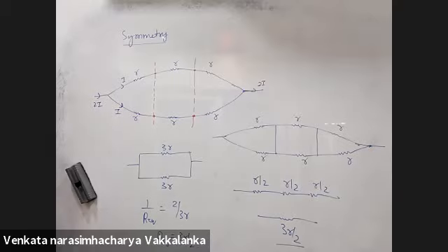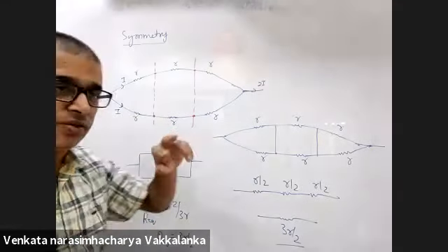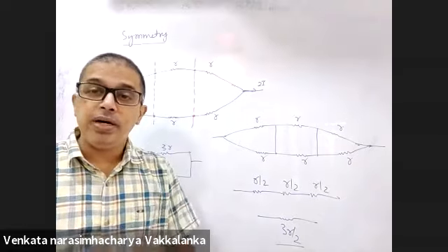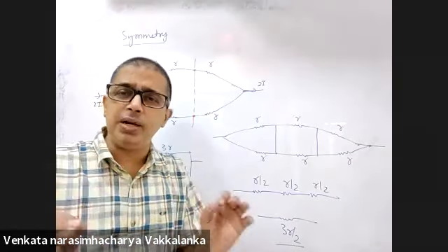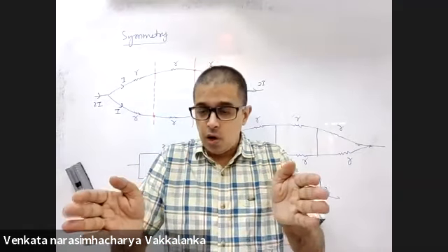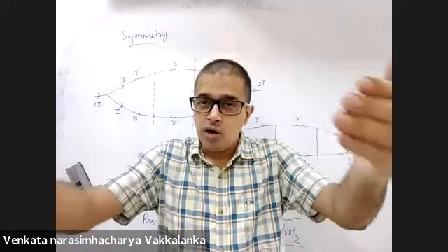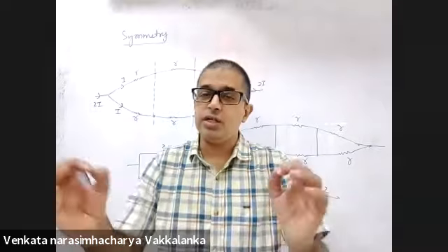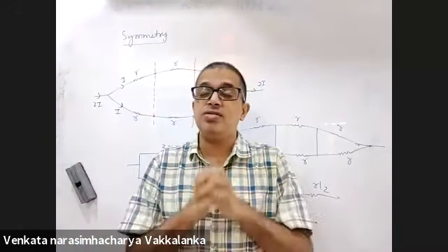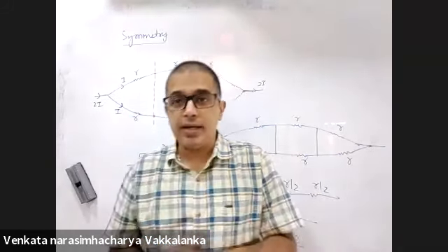So symmetry is all about recognizing equipotential points. Once I recognize, means of simplification can be more than one. But you will have to recognize. And the fundamental principle of recognition is two identical branches. After crossing one resistance each, the 2 points are equipotential. After crossing two resistances each, the 2 points are equipotential. After crossing n identical resistances, the 2 points will be equipotential. This is the bottom line.